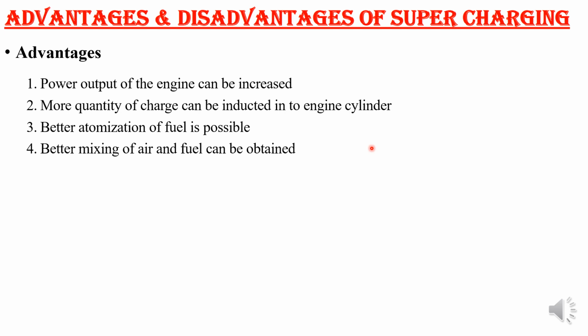a naturally aspirated engine. Then better scavenging of the exhaust gas is possible, because more pressurized air will be coming inside the cylinder, and it will push most of the exhaust gas to the exhaust manifold. Hence scavenging of the exhaust gas is very much effective whenever you are using the supercharged engine. So this is one of the big advantages.